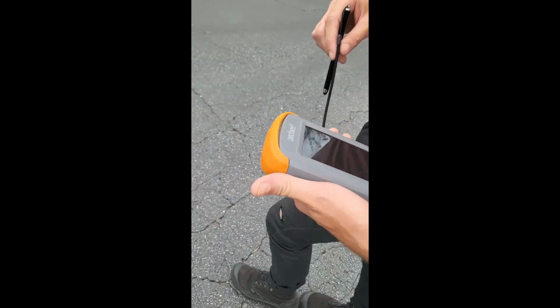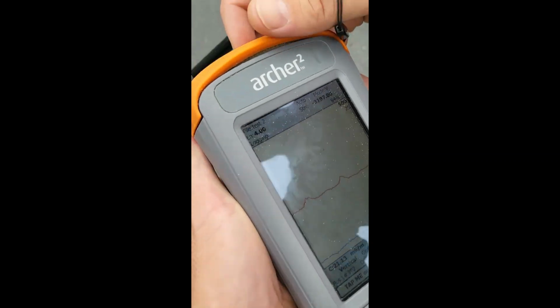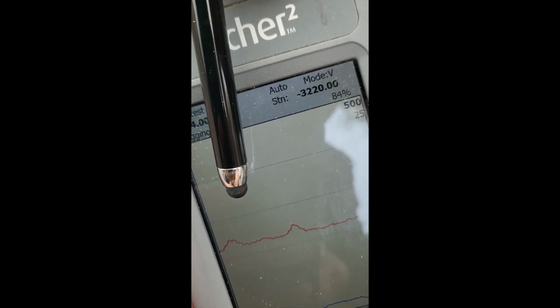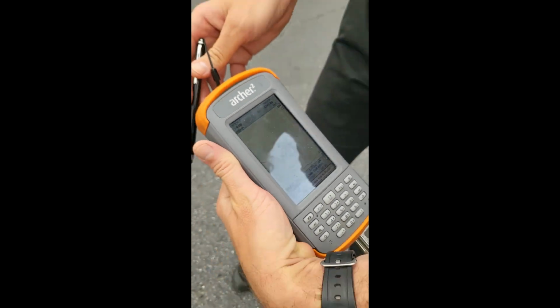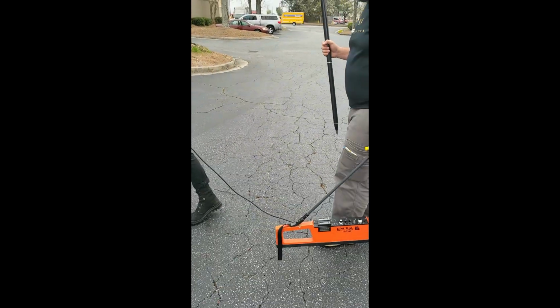And so actually if we come in, maybe we can see as it lights up a little bit, if you keep on. See those little blips, each one of those little blips, those spikes in conductivity, is when they ran over the drainage pipe. And so it is a nice tool to layer on top of GPR, because if you're over a drainage pipe and it's all the way in here, right? I mean, there's nothing out here.